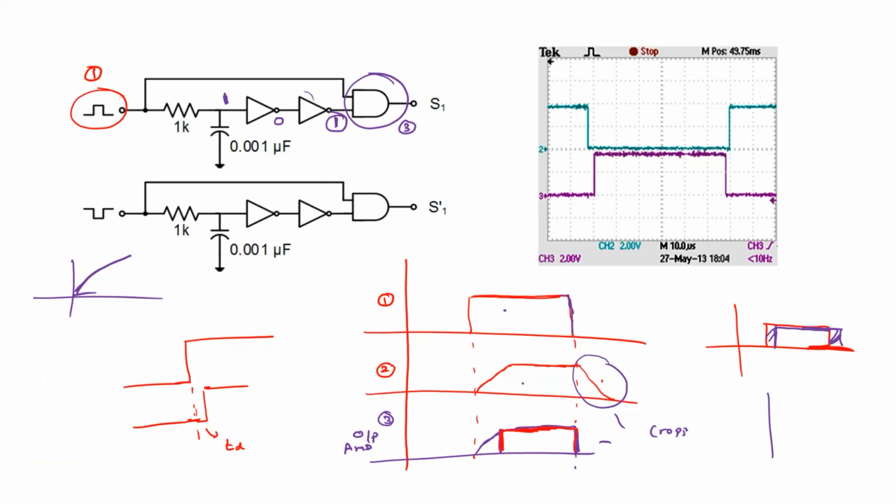Whenever some time delay is there, instead of this kind of waveform, if you want to produce sharp edges, we usually connect two buffer circuits or two NOT gates side by side, in series. That is what we follow in electronic circuits, right? In this particular setup, the time delay is dictated by the time constant RC.